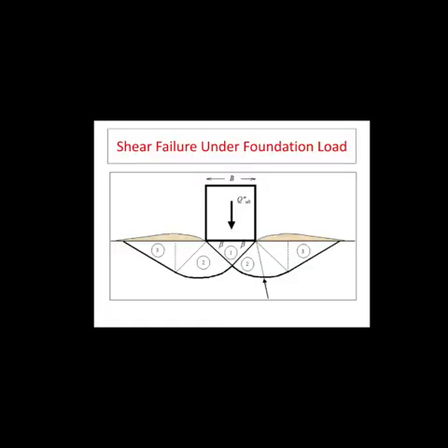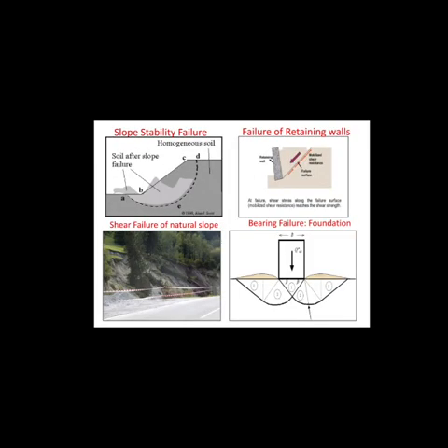The next slide shows a foundation transmitting load to the underlying soil. The evaluation of shear strength in terms of bearing capacity is very essential for foundation design. The application of the foundation pressure causes the development of shear zones below the foundation. To evaluate the nature of failure and provide analytical treatment to the bearing capacity, the shear parameters are very essential. Thus, these four examples show the importance of the study of shear strength of soils.